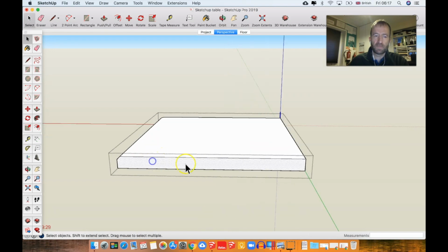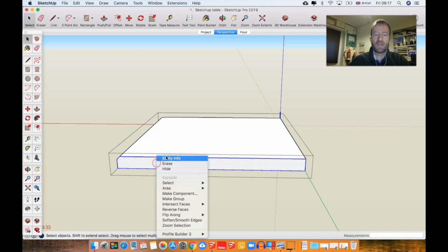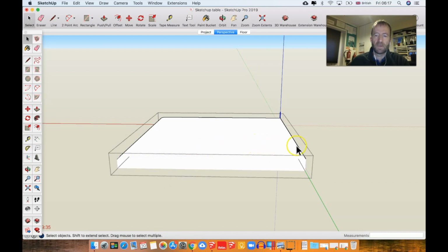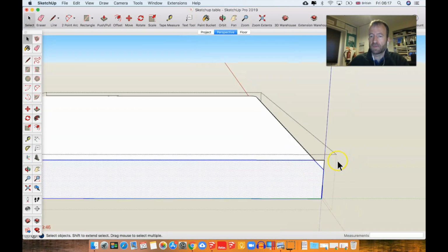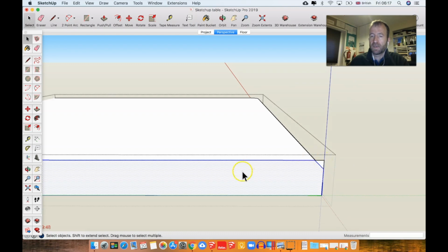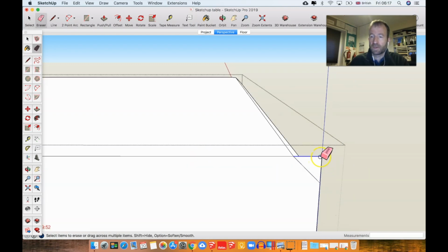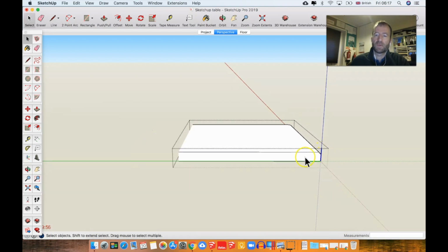Now what I want to do is double-click this surface where it meets the others, right-click and hide, which is actually just the same as Shift Erasing, but Shift Erase tends to just work on the one thing that you click on. So double-click, and in fact we have this little artifact here. What I'm actually going to do is simply erase that. So eraser, no shift, just get rid of those because we don't want them. So back to double click here, right click.